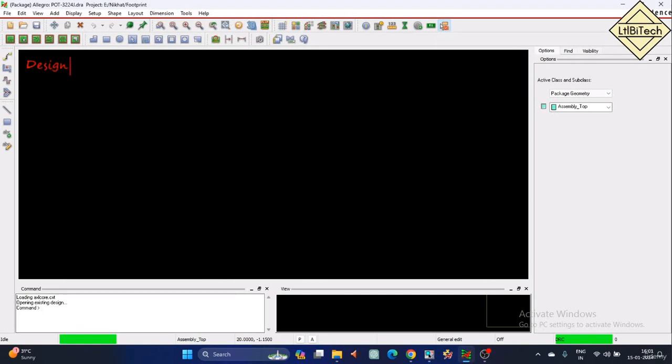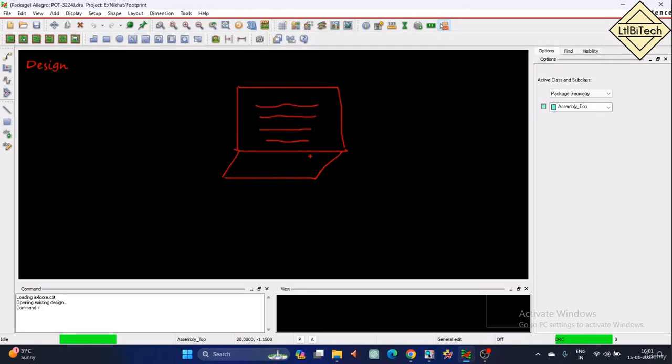The process begins with the creation of the PCB layout using computer aided drawing. The computer aided drawing is where we are going to create the schematic part. So we are going to create the symbols, we are going to create the footprints, and then we are going to create the PCB board, and then do the placement, and then do the routing. All of this comes under the computer aided drawing design software. As designers, we define the placement of the components, we do the routing of the components, and we trace all this and other specifications. So the first part is the design.